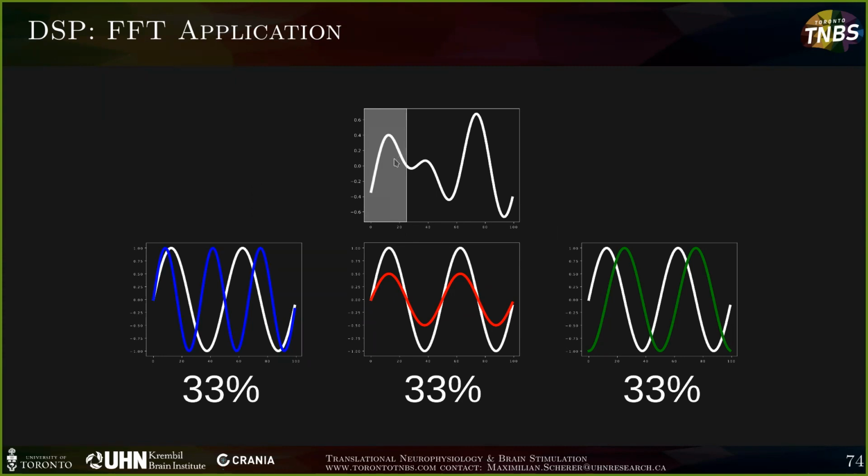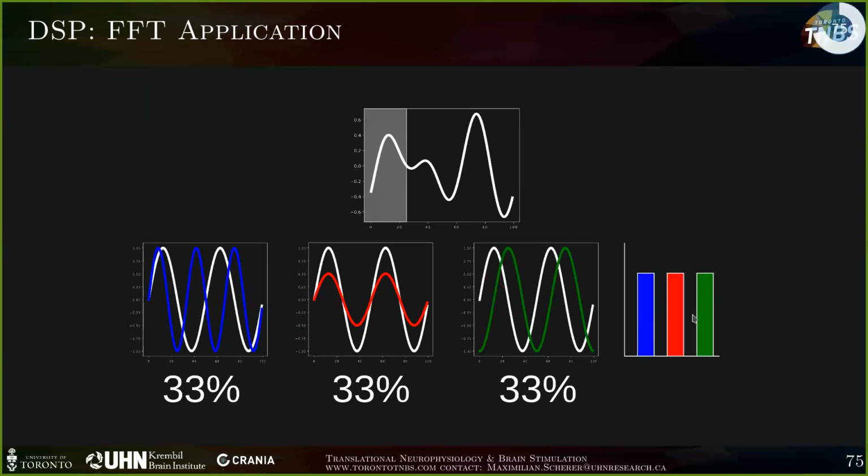If we apply the FFT to that, we basically get a complex representation of sinusoids, which are telling us the amplitude, the frequency and the phase of the sinusoid, and then we can further transform that information to create a power spectrum density. And that power spectrum density is going to tell us how much of a specific sinusoid is within that signal. If we take a look at the signal here, that's basically an equal distribution of those three sinusoids. And usually that's represented in this form here, which is, as I already said, a power spectrum density, usually a histogram or a line plot.